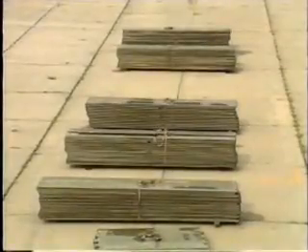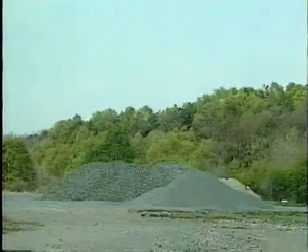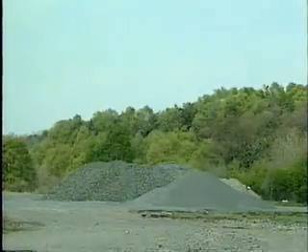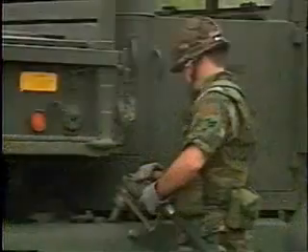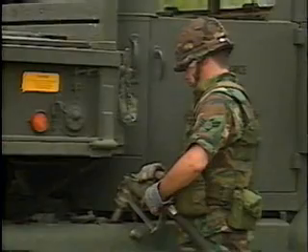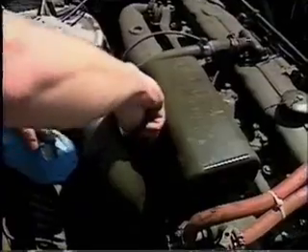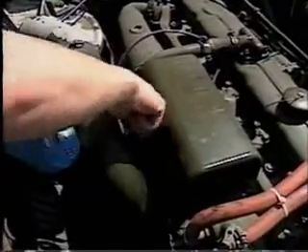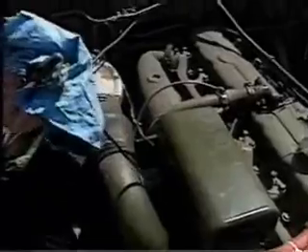Hard-to-move material like AM2 and fiberglass matting, sand, gravel, and rock fill material should be pre-positioned in stockpiles at key locations around the base. If possible, a vehicle maintenance mechanic, spare parts, and refueling capability at the dispersal locations will help to ensure that recovery vehicles and equipment will continue to operate if the main fuel and maintenance facilities are damaged or destroyed.